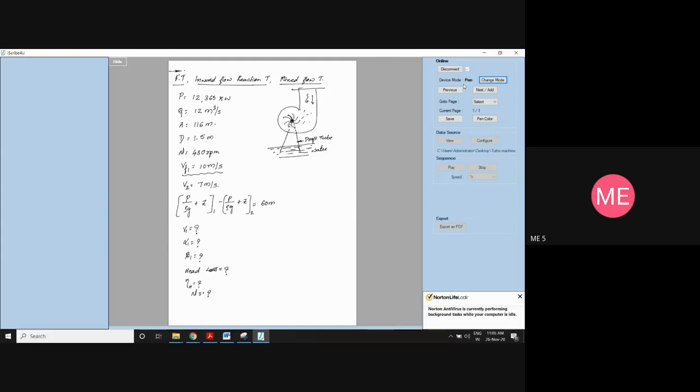So what is happening? I'll draw the side view of this figure. See, let us assume this is the turbine, and this is the penstock. From the penstock, water will enter and swirl all around the turbine like this, and from the center the power will generate. That means here there will be a shaft and generator. But the water has to go out. Where will it go? The water will be connected to a tube called the draft tube. It will be like this, and this draft tube will be dipped inside the water. You check out in the fluid mechanics lab while doing the experiment of this Francis turbine. You come to know how it is connected.